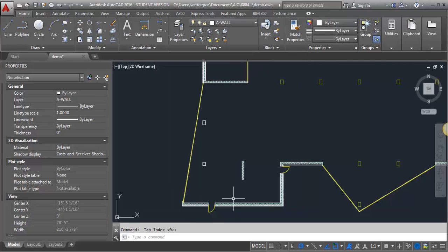And then if I click OK, now I can draw a line, and you can see that as I near that 80-degree angle, it kind of locks in, and I get that dashed green line that indicates that it's locked in. And by the same token, if I go close to the 170 here, it does the same thing. And again, it'll do it with the 260 and the 350 as well. So you can use the polar tracking then to make sure that you're drawing at exactly the right angle.